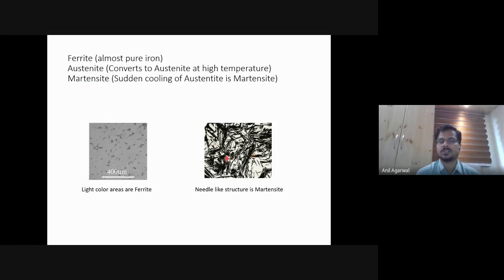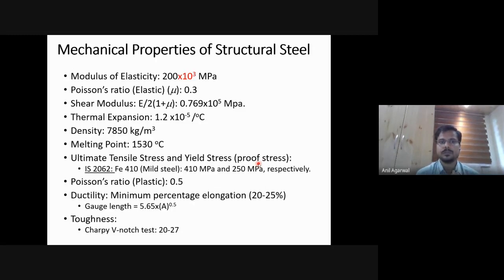And the martensite structure, if you cut another specimen, polish it, and look microscopically, looks somewhat like this. You will see a lot of tiny microscopic needles forming, and these needles almost look like ice needles, right? If you let ice frost or let water frost, it forms this kind of needles, which basically provides a very high level of brittleness. Okay, so higher strength but more brittleness.